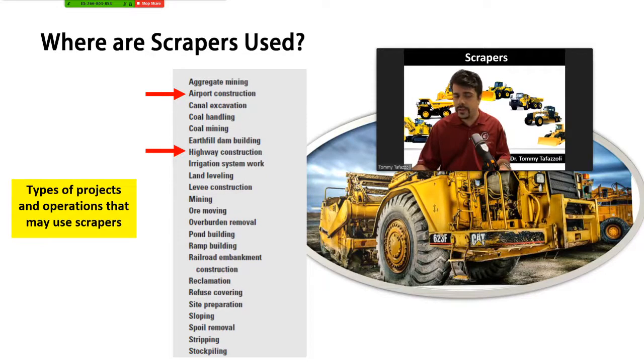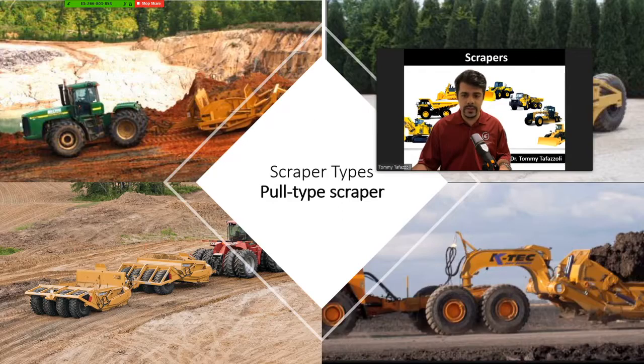Obviously for highway construction, for land leveling, for overburden removal, for railroad embankment, for site preparation because it has some clearing and grubbing capabilities, and for stripping. Okay, for all of them, scrapers can do the job for us.